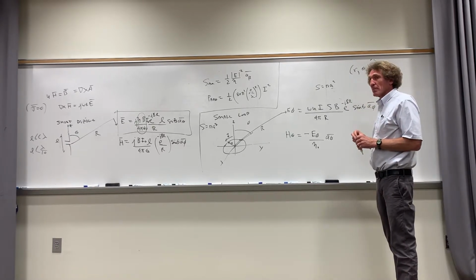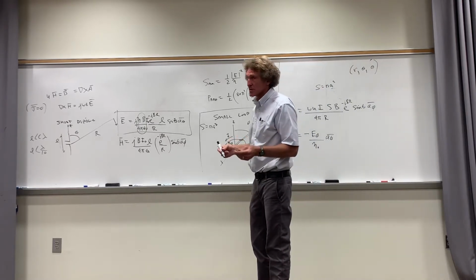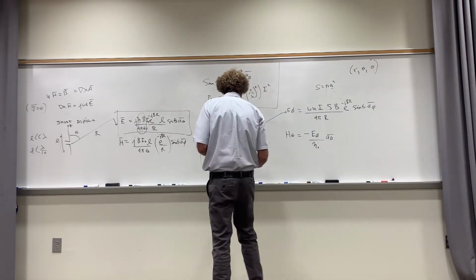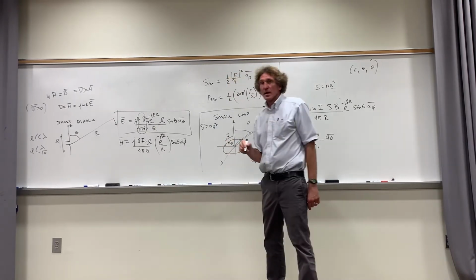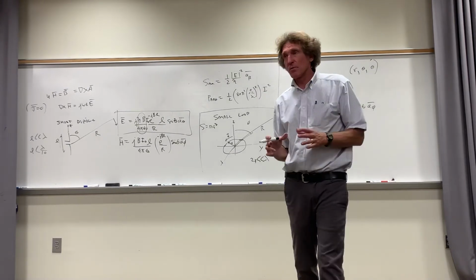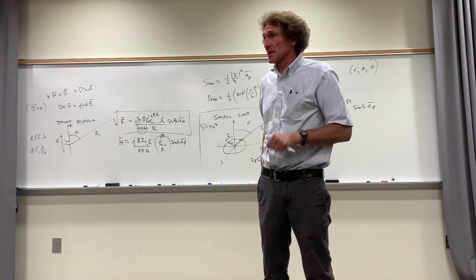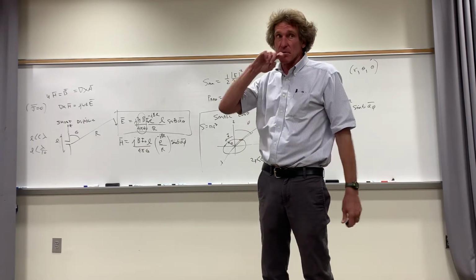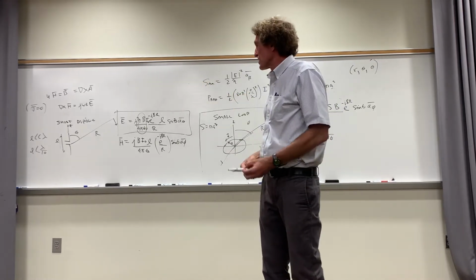Now the small loop antenna, by the way, when I say small loop antenna, you should ask yourself, what does he mean by that? What it means is the diameter, or 2A, is much less than a wavelength. Because the minute that loop gets to be of the order of a wavelength in diameter, things change rapidly. Then it doesn't act like it. Then these characteristic equations go out the door. Are you with me? And it's just like you're going to see for a short dipole.